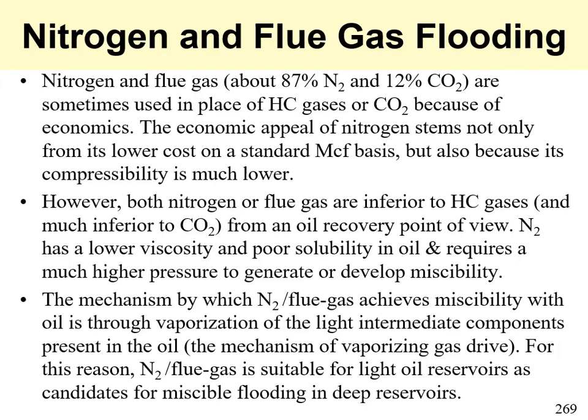So a higher pressure is required to develop miscibility. And I had earlier mentioned the mechanism through which miscibility is achieved for these gas systems. And because it uses the vaporizing gas drive mechanism, nitrogen gas or flue gases are suitable for light oil reservoirs in deep formations.